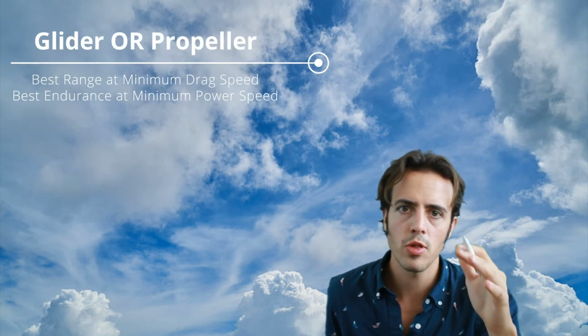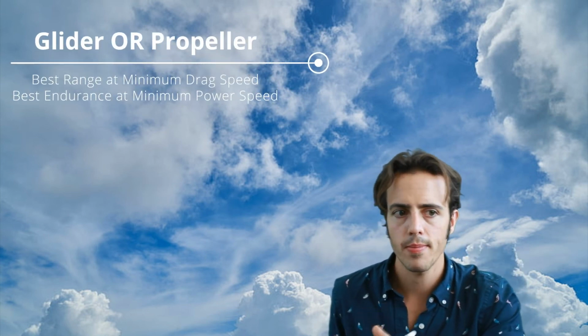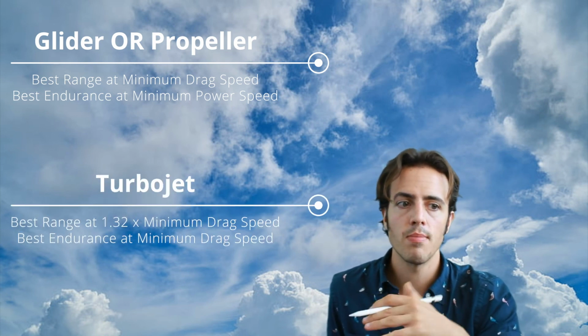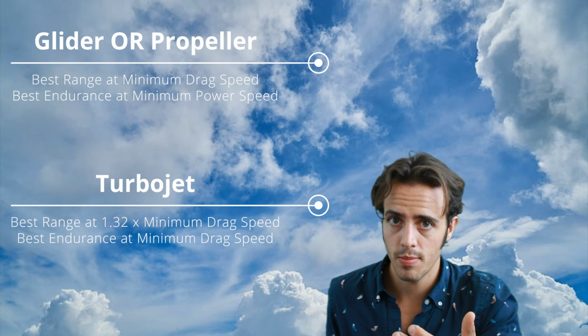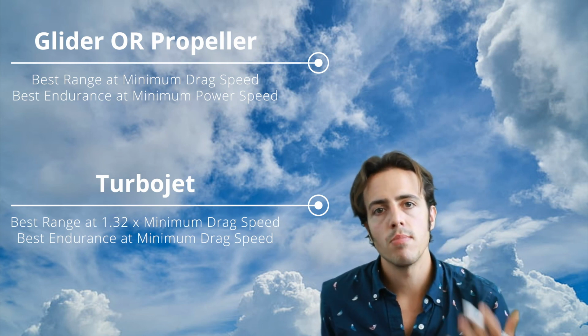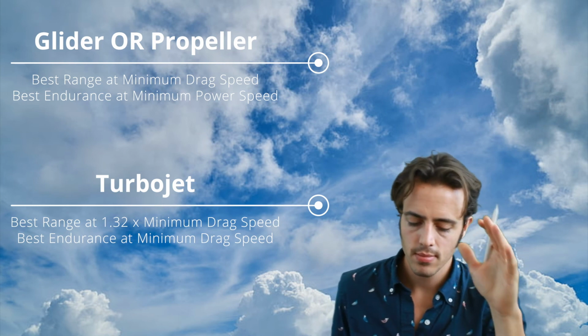And we then showed a few things. Let's talk about them all. So for a glider, we showed this already. We showed that our maximum endurance was at the minimum power rates. For a jet aircraft, maximum endurance is at the minimum drag speed instead. And if we're in a propeller aircraft, our maximum endurance is at the minimum power speed again.